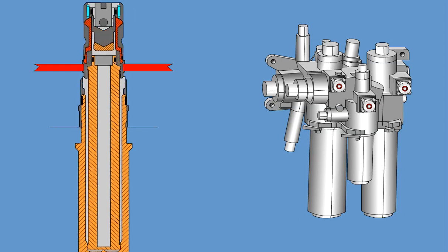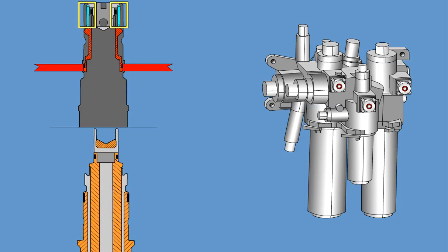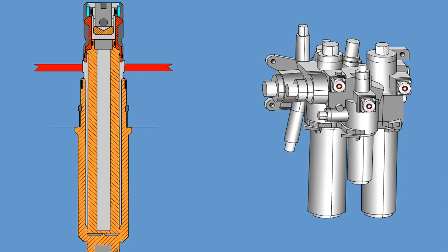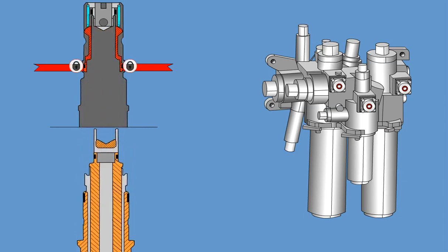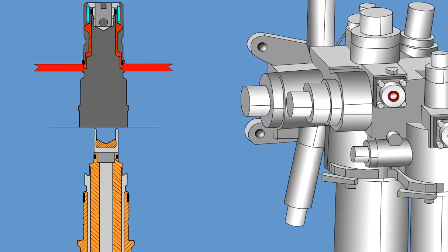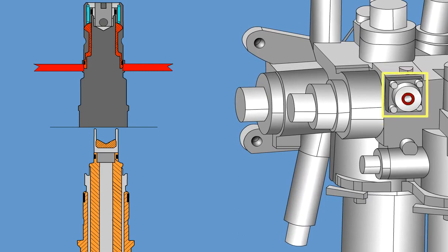The shutoff head is spring-loaded to the closed position and is normally held open by the top of the filter element. As the filter bowl is removed, the shutoff head will descend and close off the opening of the filter bowl housing. Should a filter bowl be installed without an element in place, the shutoff head will only partially open, causing sufficient pressure drop to operate the relevant differential pressure indicator.